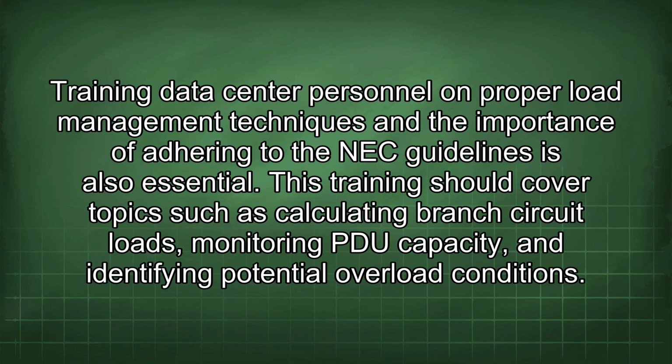Training data center personnel on proper load management techniques and the importance of adhering to the NEC guidelines is also essential. This training should cover topics such as calculating branch circuit loads, monitoring PDU capacity, and identifying potential overload conditions.